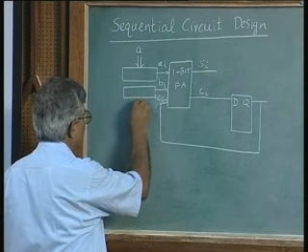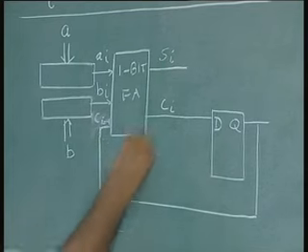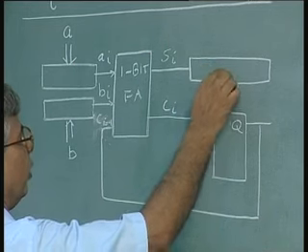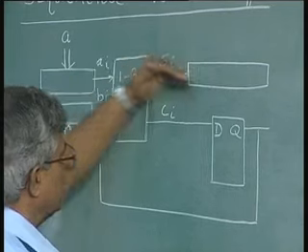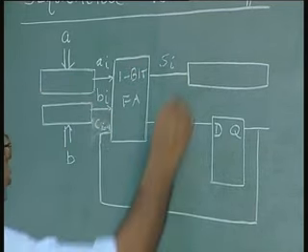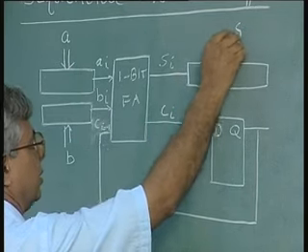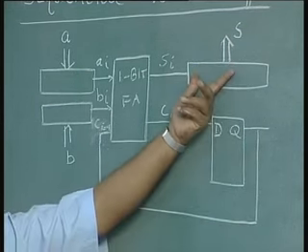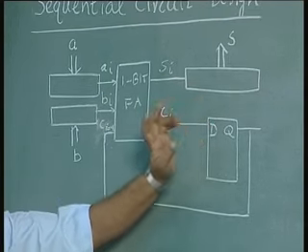B, whatever is the number of bits, and I am going to put the result also in a shift register, wherein as Si gets stored, it gets shifted along the way. So, at the end of the operation I will take S from here, and if I provide a sufficient number of bits here, the last carry also will be taken into account. So, I do not have to provide an extra register for carry.